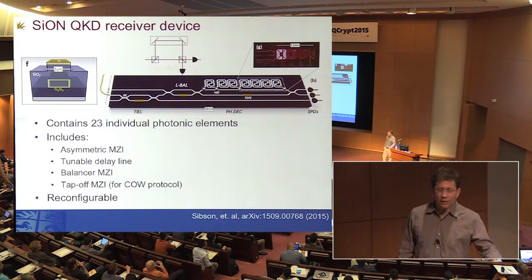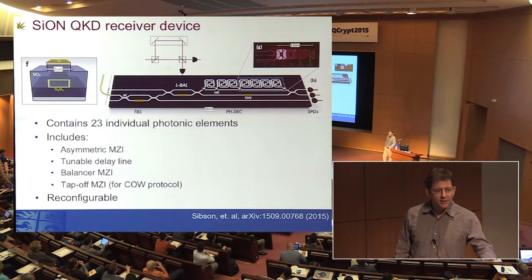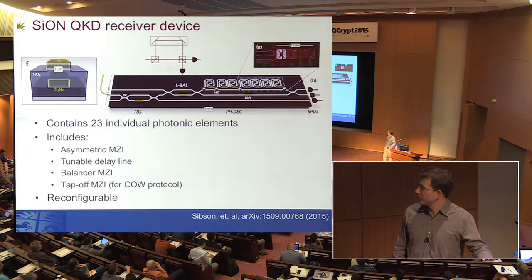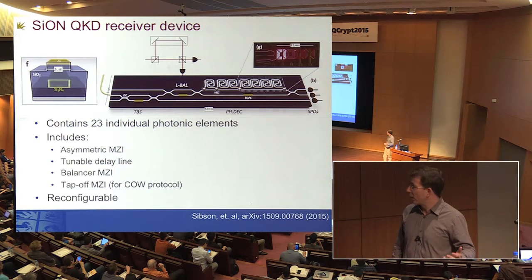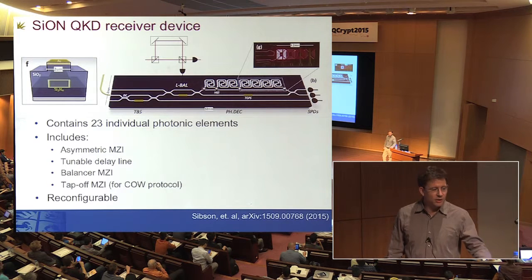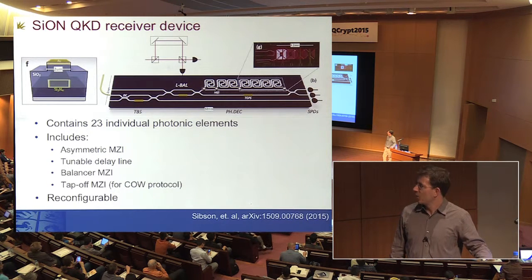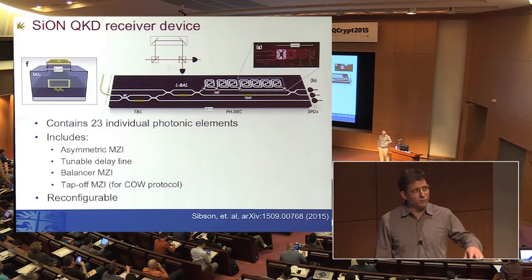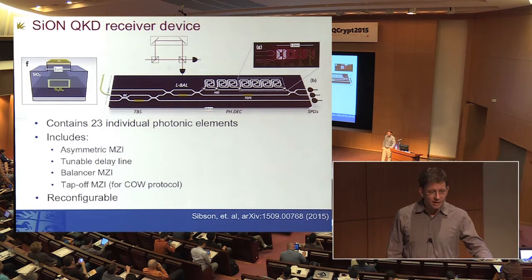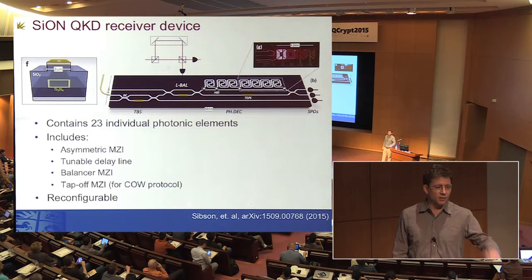To get around that, we do have ways. It's something called photon source multiplexing. What it requires is to integrate active and fast feed-forward switching into these systems. But it's well understood. It's an idea that's been around since about 2001. We know how to do it, and that's what we're basically working towards, effectively an actively multiplexed, deterministic on-chip photon source. And once you have that, then scaling up becomes not a problem in terms of the probabilistic nature of the sources.